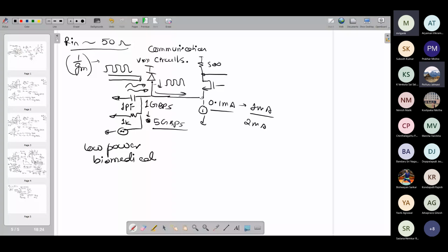There, people use photodiodes also for certain applications. There is one application which is called PPG, where there is again a use of photodiode. The idea over there is also simple. The way it works is the same thing. The only thing is, first you have an LED source. So here there will be an LED which is driven from the chip. The LED is given the drive current, and it produces some light, and this falls on the skin. So basically you put your finger over there and it falls on the skin, and some part is reflected,